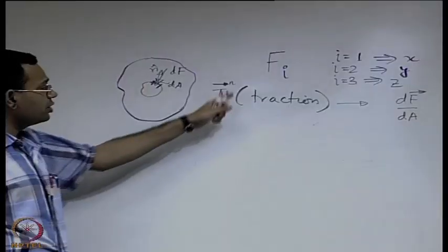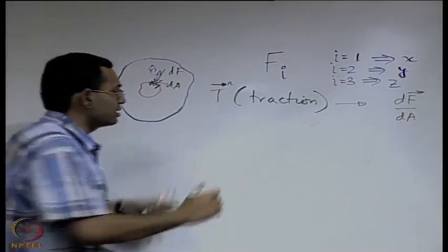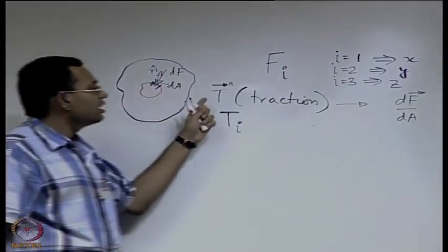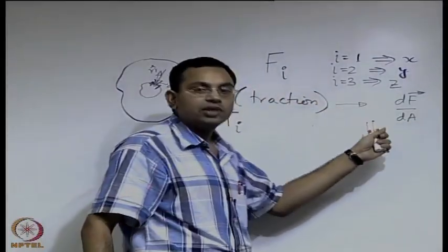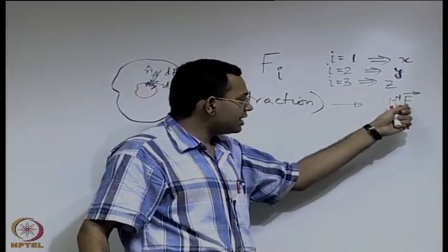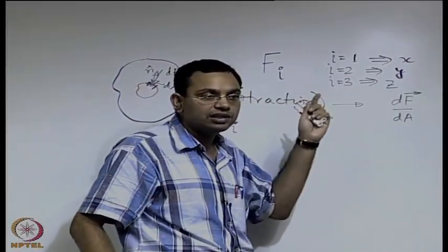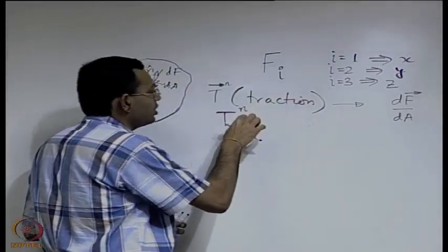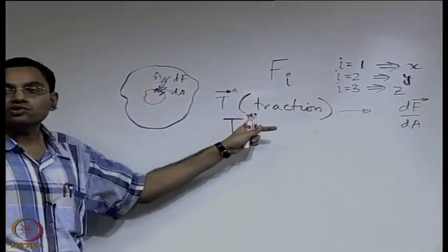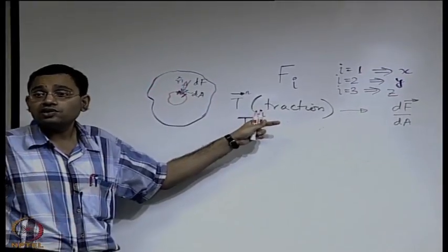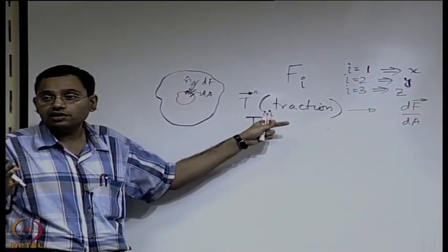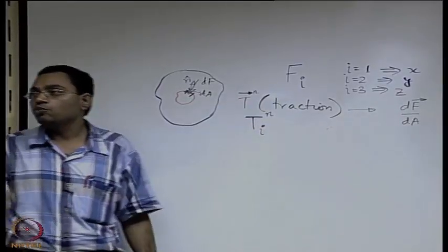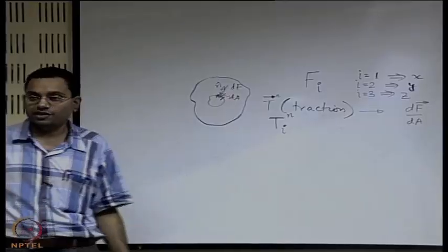But when we denote this traction vector, yes, it has components because it is like a force per unit area, and based on the direction of the force it has its own components, but its specification also depends on another index n, which denotes the choice of the area orientation employed to calculate this t. So, it is something more general than an ordinary vector.